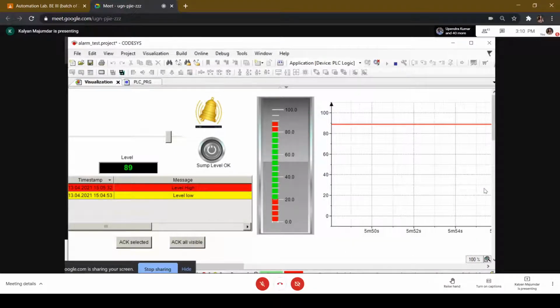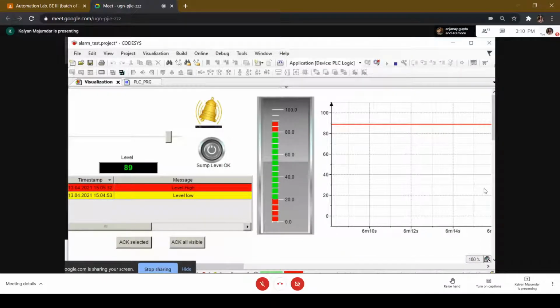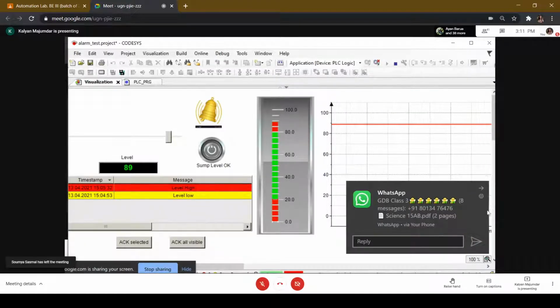And the standard practice is all alarms are logged, just like the trend is stored within a historical trend server, it's stored within the hard disk. All alarms that are generated and all alarms when rectified, this information is stored within the hard disk. So that again, if you have a fault, you can find out what was the actual reason of the fault, what alarms occurred, whether they were attended to or not, whether they were rectified or not, why this particular fault occurred. So all kinds of alarms are by default logged. Logged means that information is saved within the hard disk.